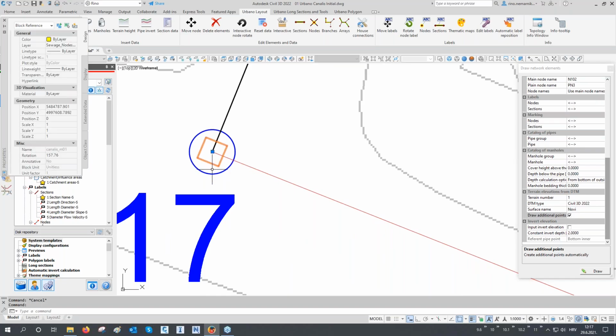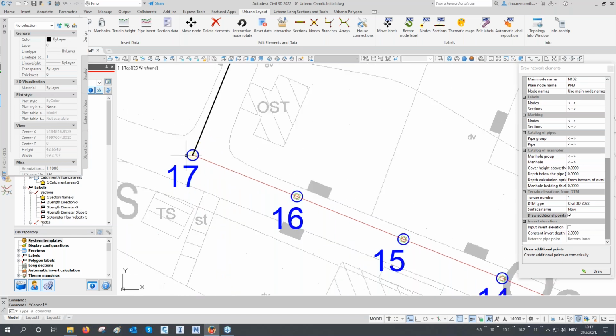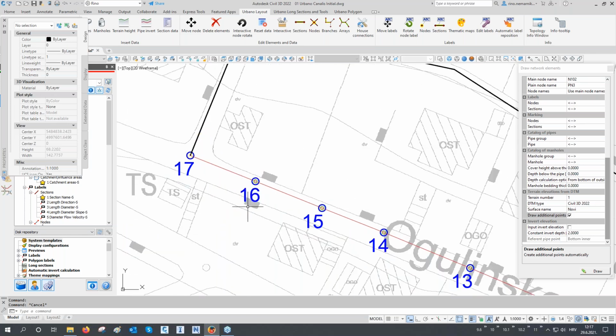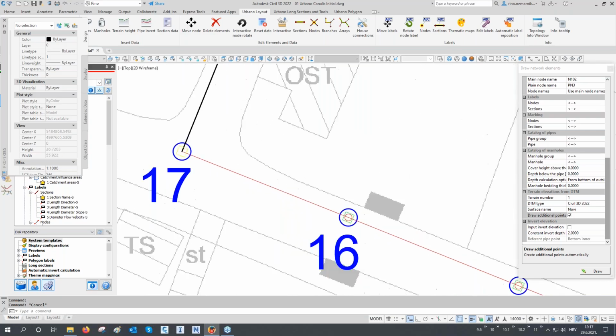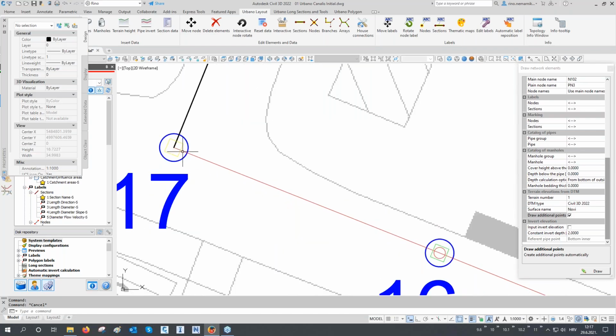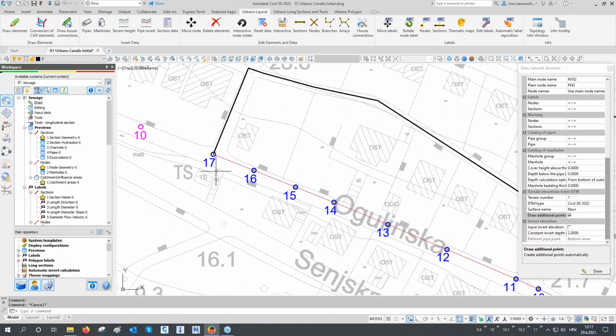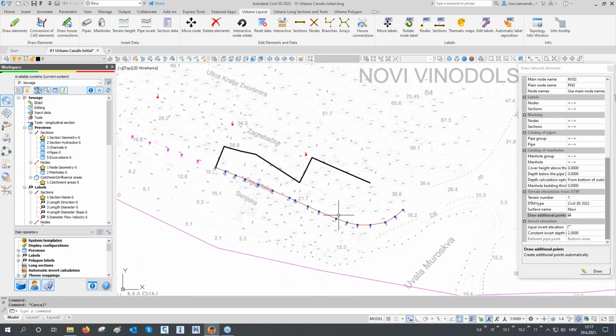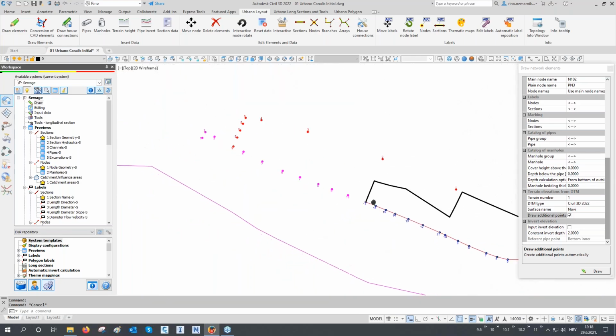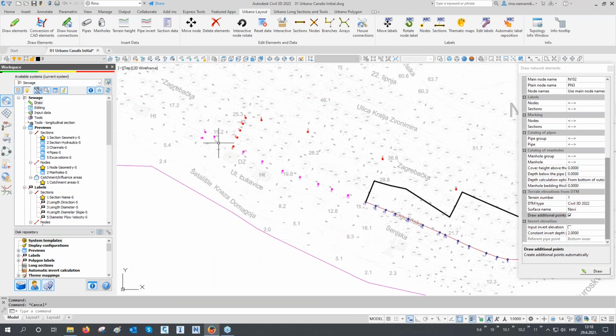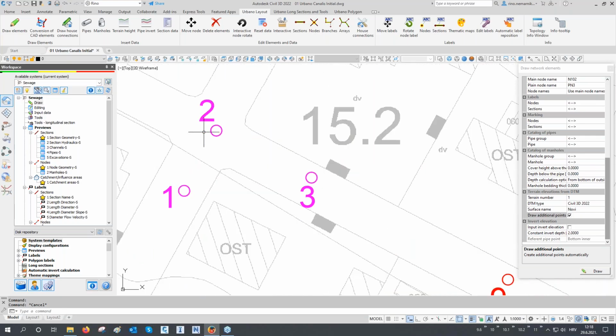And here it is. We can see that these are basically AutoCAD lines and also AutoCAD blocks. But this is something that we call styling. And later on, I will show you how you can use different stylings. You can also show this in different styles with realistic pipe and manhole dimensions in 2D or in 3D. Okay, so now we have drawn one branch, or one array, as we call it in Urbano. And now I will continue drawing, but now following these helping circles, I will start from here.